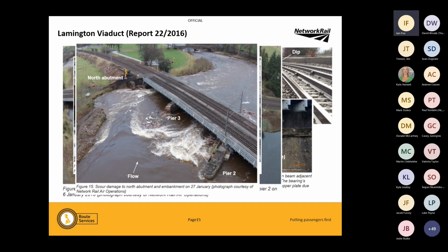The original damage was fine, but the way that we tried to repair that caused a problem. That was 2016, when we understood scour a bit more. So it's not something where you think, well, we understand it now, the problem goes away. It doesn't. It still requires people who understand scour to look at some of these schemes and look at these repairs and be involved in the methodology before we start blocking rivers off.